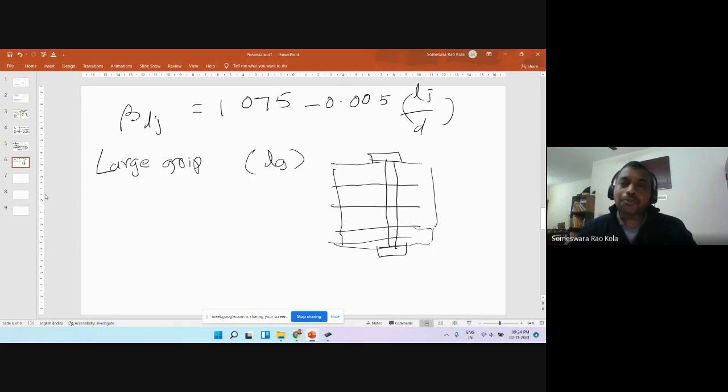So we are going to reduce the strength of this bolt in this scenario. The reason being, in such a scenario this shank is subjected to bending, depending on the pull and push of all these fellows. When there is deformation like this, obviously the strength of the bolt is going to reduce. That's why we are trying to account for reduction of strength in these scenarios.